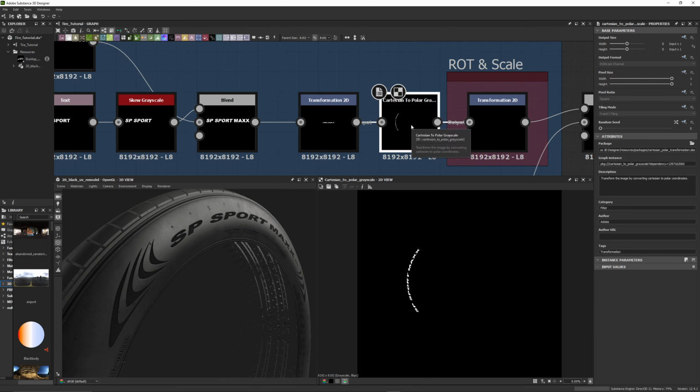All right, so for the Dunlop, we use this Rockwell Extra Bold, font size 0.12. We kept it in the center, but here we did scale it on this first text transform essentially to squash it. So I've got a bit of a skew on there. We use the transform here to scale it down, and we mirror it horizontally and vertically. Cartesian to polar, rotated essentially -90.